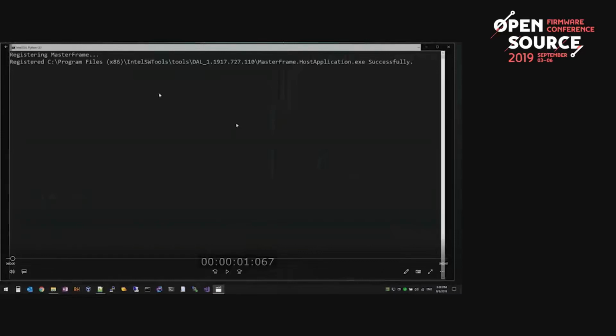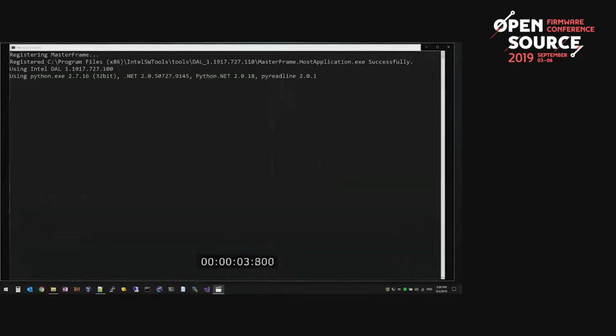And this isn't one of the breakpoints that you have to go code and build. It's by default part of the Intel System Studio drop-down: break on SMM enter. It's built in. Among the other things, there's VM enter, VM exit, SM enter, SM exit, reset vector. There's all kinds of cool stuff there.